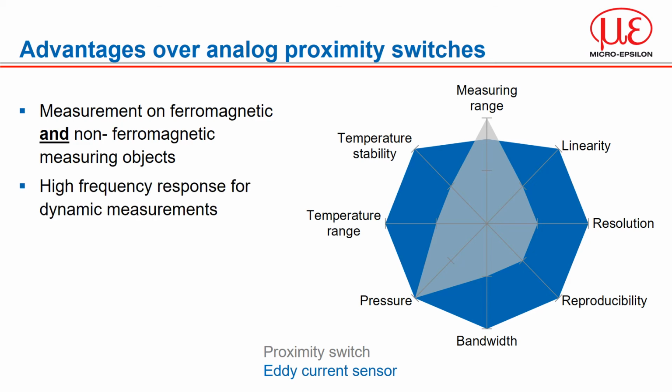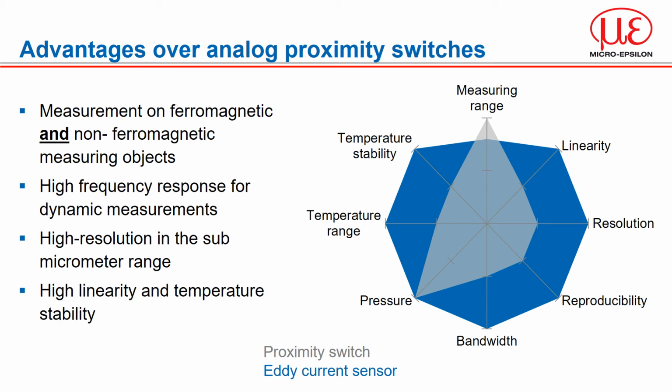The high carrier frequency used allows for very fast response times, and our calibration process gives exceptional measurement performance. In addition, the high carrier frequency also means that the eddy current sensor is unaffected by magnetic fields. There is no ferrite core to demagnetize.